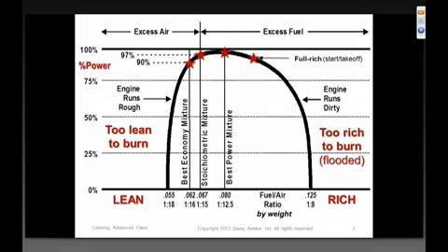But it's the fuel-air ratio where the amount of fuel and the amount of oxygen are as perfectly matched as possible, so that at the end of the combustion event, there is very little unburned fuel and very little unconsumed oxygen. The stoichiometric mixture is where we get peak EGT, so that's how we identify it, with an EGT gauge. As we continue to lean onto the lean side of peak, we get to best economy mixture,